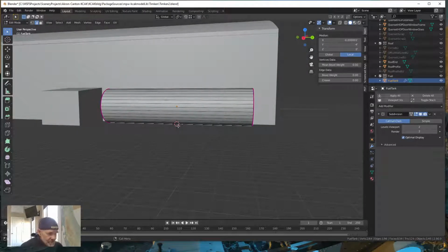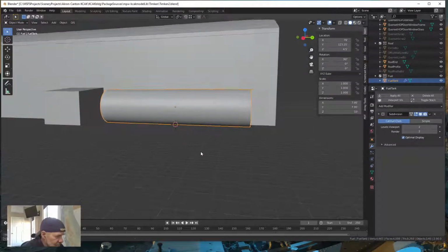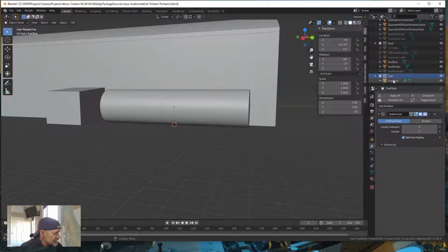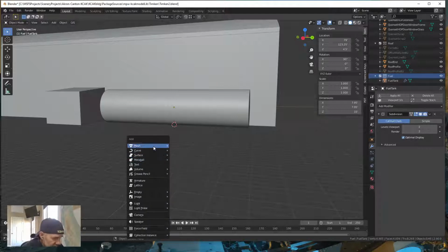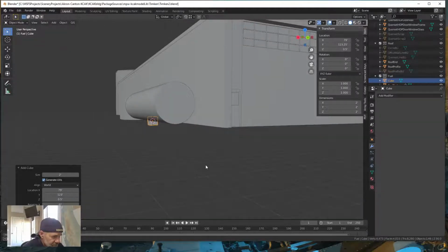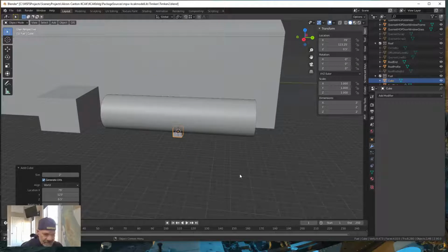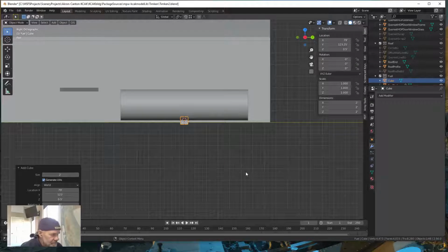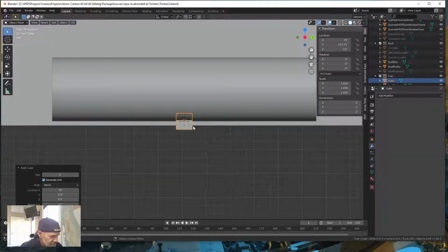All right, so with your 3D cursor there, get out of edit mode, and you're still in the fuel collection. Do a Shift A, and let's add a mesh cube. So it places a cube right there. We're on the right side of our building, so if I did a tilde-R, notice that our cube is 6 inches into the ground, because this is the ground level. Our cube is 2 by 2 by 2 feet by default.